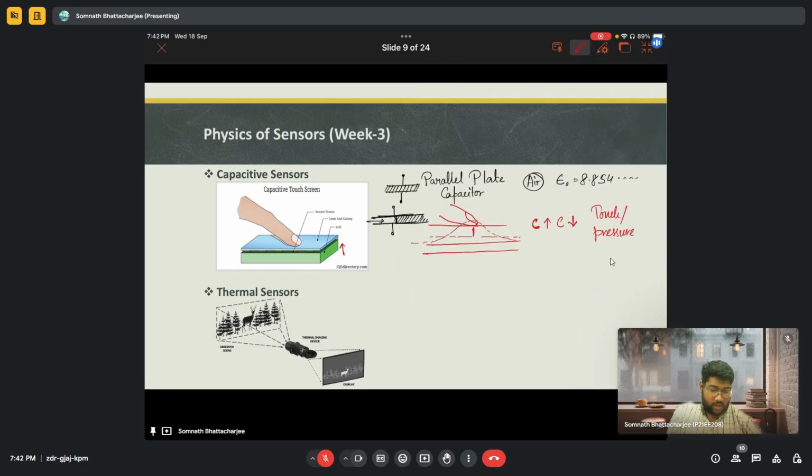As I am writing something on my phone, it will detect how many touches there are. It may be in a grid kind of structure where you have multiple capacitors and sensors, based on how an image can be divided into pixels. Multiple capacitive sensors can be attached together to form a structure like this.